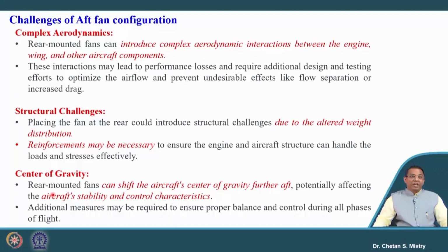Let us see what the challenges are. As we say, when we are putting these rear mounted fans, that will be increasing the complexity in terms of aerodynamics, because we will be having interaction of the wing, and other aircraft components may be coming in the flow path of this engine. That is what will be making the design for this configuration very challenging. At the same time, we need to take care of flow separation, and we need to be careful about increased drag.